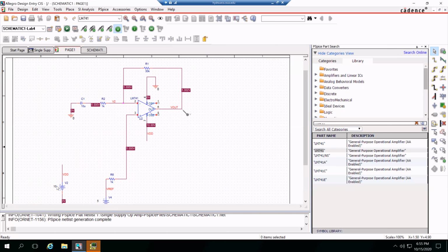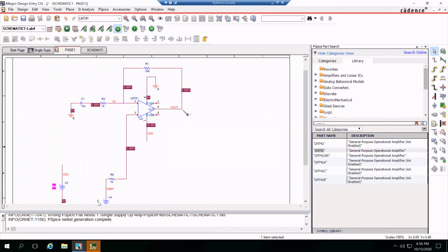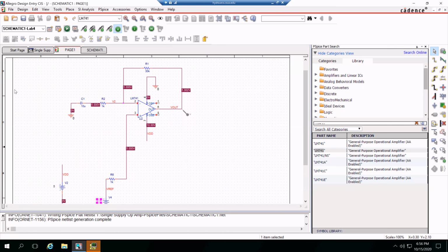I'm going to actually come back now, and I'm going to change this to 5. And I will change this to 2.5. So it works with your lab. I'm going to save that, run it again. Voila. Okay, so what are we seeing, right? VREF coming in, you got 2.5 here on VREF, 2.5 here, 2.5 on your output, 2.5 on your input. Golden, looking great. And you got 2.5 going through this resistor, and this capacitor is an open, right?